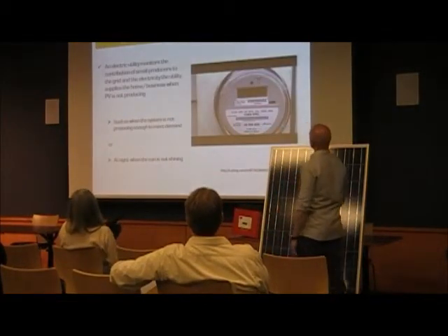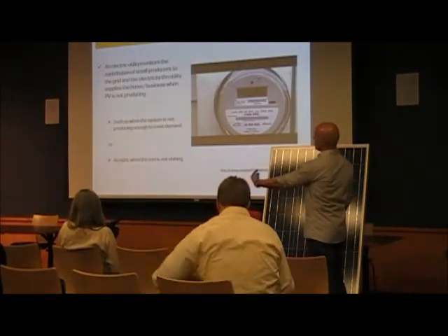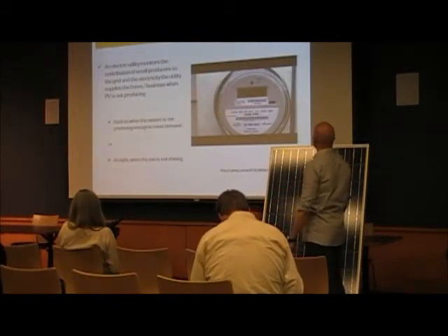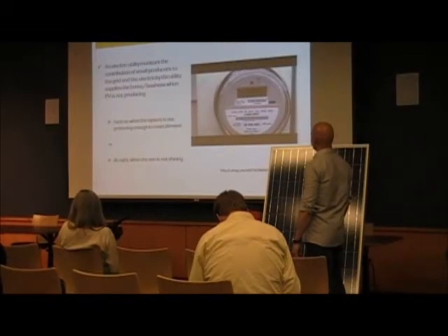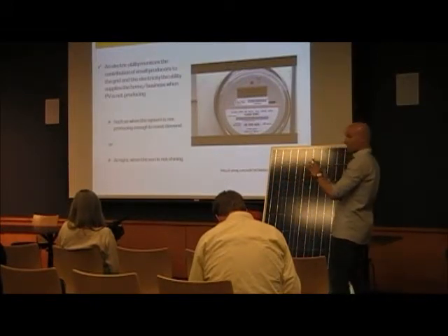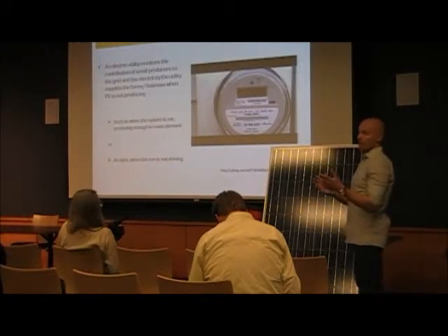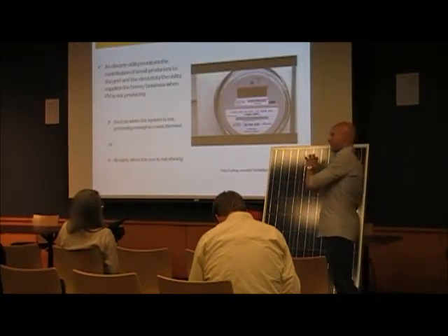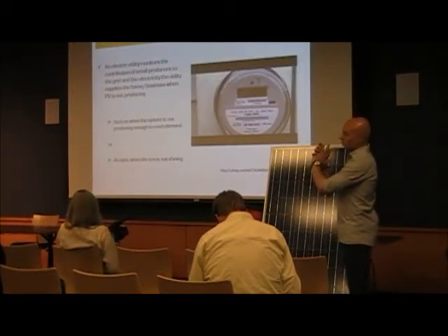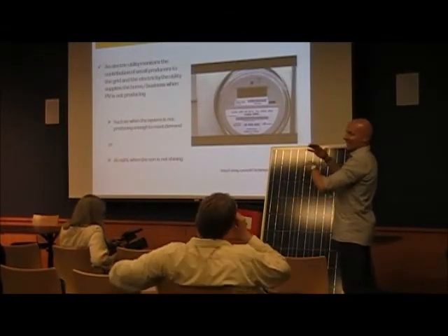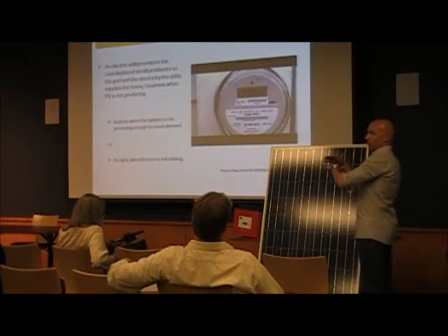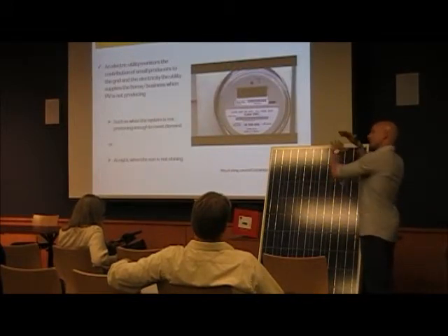And then there's your meter, and then your meter starts spinning backwards, which is what we all like to see. It's pretty cool. This is an electric meter, so you don't get the kind of effect of that. When you install these, the utility will come and give you a bidirectional meter. Think about it as you're pulling energy, you're pushing energy out, and then they net it at the end of the month. And if you have more than what you bought, then they move it into the next month.